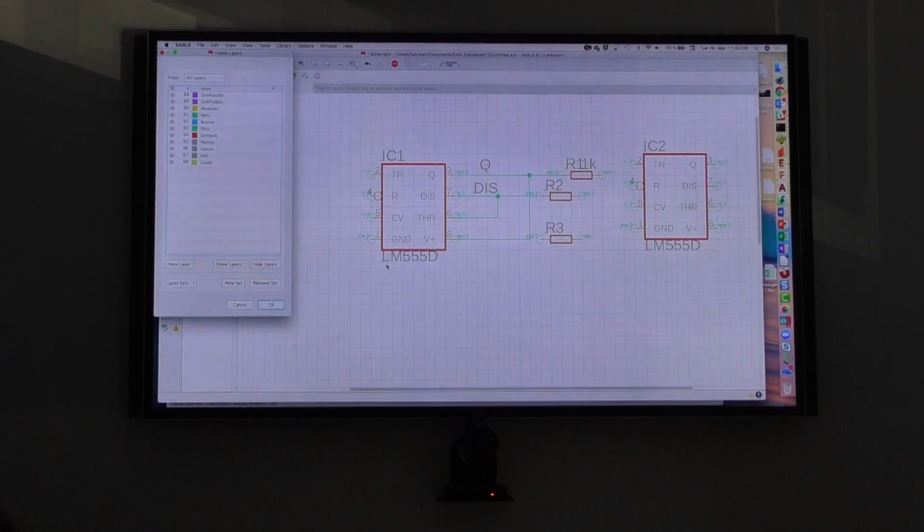There's some simple logic behind where we try to point you to some situations in the schematic and say, hey, is this correct or not? Yeah, for 3-pin components or more pin components, if there are pins left open and they are not input, output, power or whatever, if it's passive or I/O, that's what we have, and it does not complain. If we have a direction, it would complain because I expect an input pin that should be connected. So there's some logic behind.